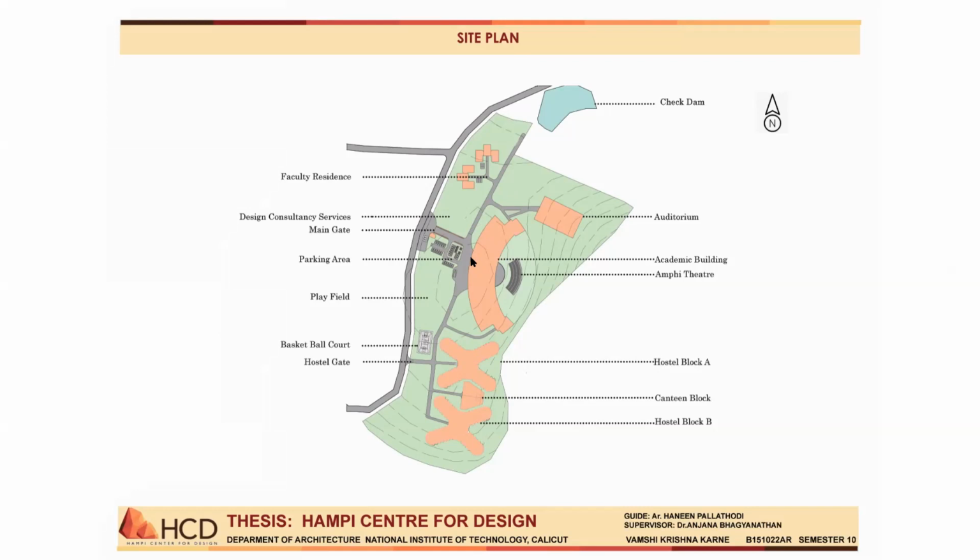So I have placed these buildings also facing towards the west, so that I can design in such a way that I can take the advantage of the light, but avoid its disadvantages like more heat build-up in the buildings. So I have taken that, and the wind direction was considered mainly in designing the site plan.